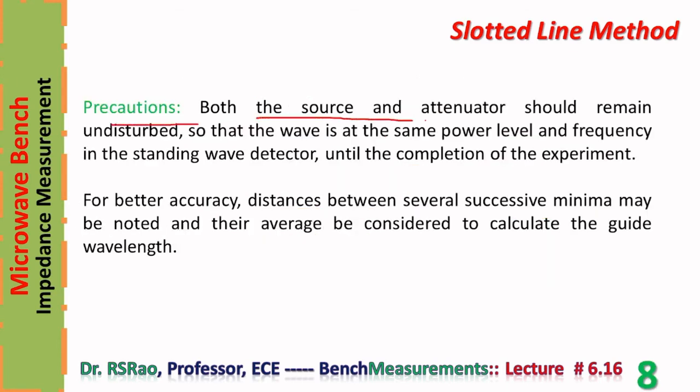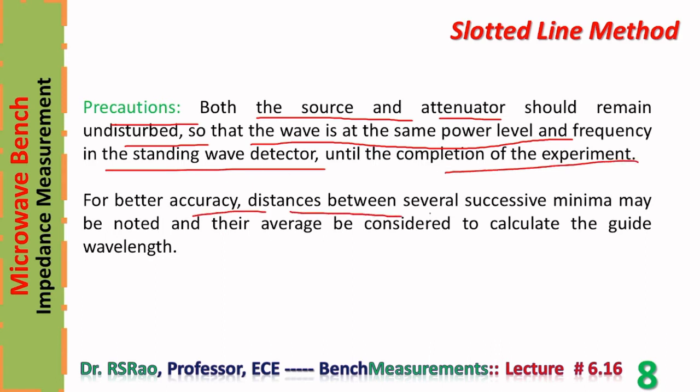Precautions: both the source and attenuator should remain undisturbed so that the wave is at the same power level and same frequency in the standing wave detector until completion of the experiment. For better accuracy, distances between several successive minima may be noted and their average considered to calculate the guide wavelength.